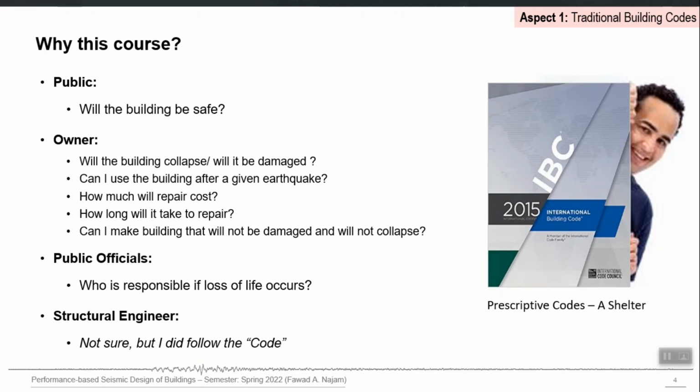So, in performance based design, you can actually tell what damage you are going to sustain for what level of earthquake, what cracking, what yielding, what concrete crushing or steel yielding you might expect at a certain level. So the performance is clear. You can directly tell the client that if tomorrow this much level of earthquake occurs, this much repair cost you should expect, and if it is acceptable, then the design is okay, right?